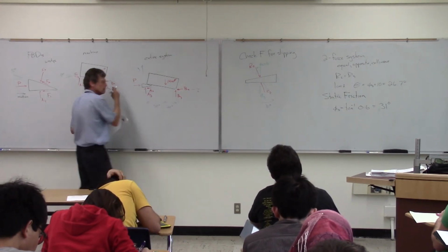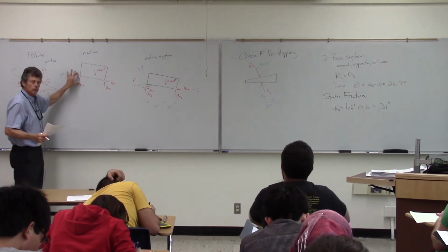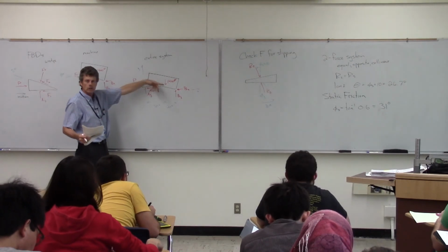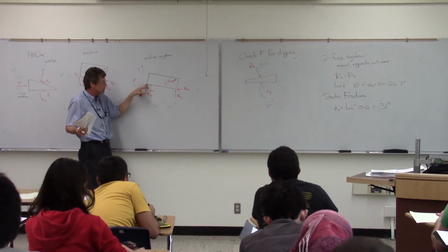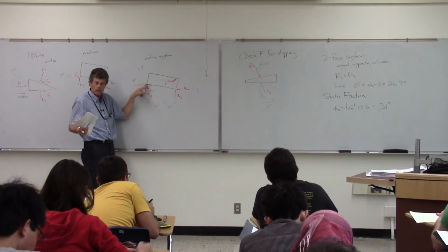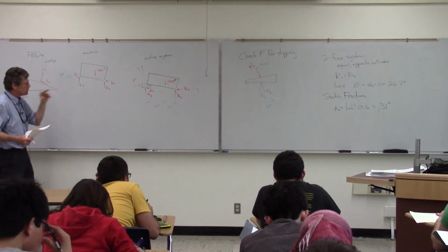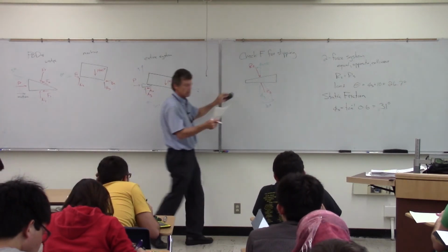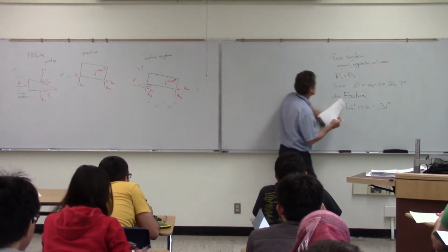And again, look at the whole system. Note that I'm not drawing those internal forces there because they're now internal. It's in contact. It's internal to this free body diagram. So those forces don't exist as far as this free body diagram is concerned. This is glued together as far as this free body diagram. But with this free body diagram, I can actually start solving for some things there, noting that Bx and Ax are acting along the same line of action.